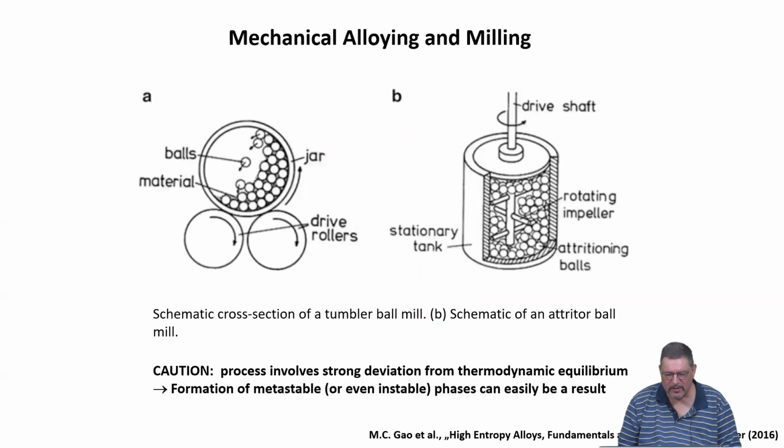Yeah, this is maybe not so important. If you want to do powder metallurgy, you all know ball milling, and there are two general types, like a tumbler or a Spex ball mill. They just are different in terms of how much energy you put into your material, which you either blend or just severely deform.